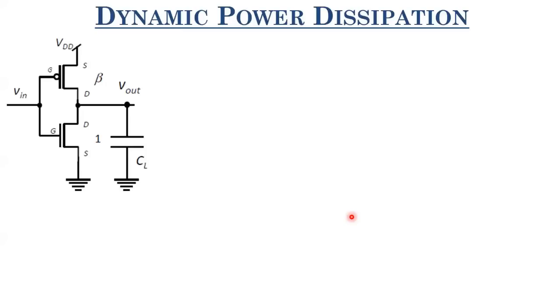Now let us talk about the dynamic power dissipation. So when does the dynamic power dissipation happen? Whenever the output is switching. And we saw in our preliminary discussions that this power, or energy, is taken from the supply only when the output goes from 0 to 1. So whenever the output goes from 0 to 1, it takes in some amount of power or energy from the supply. Let us say that F0→1 is the frequency of changing the output from 0 to 1.